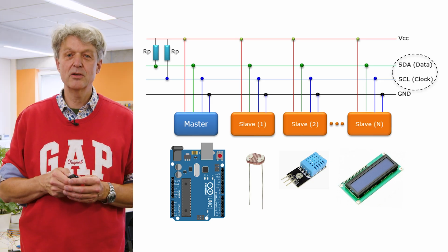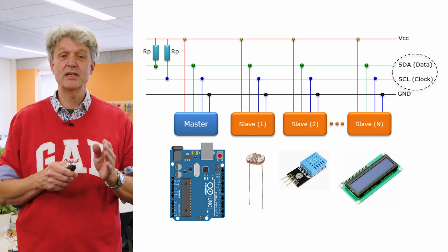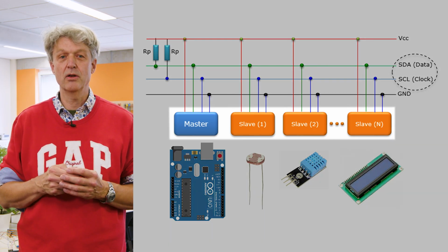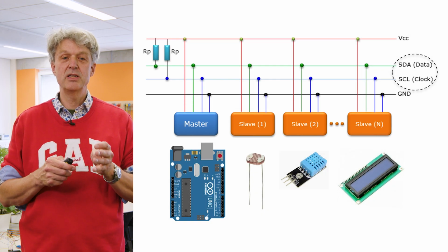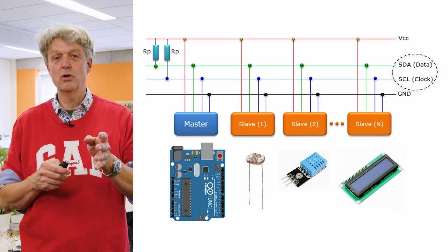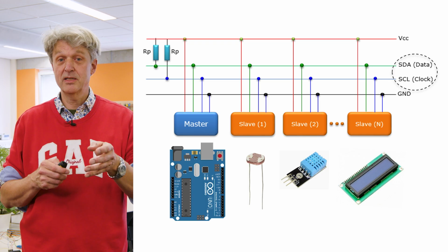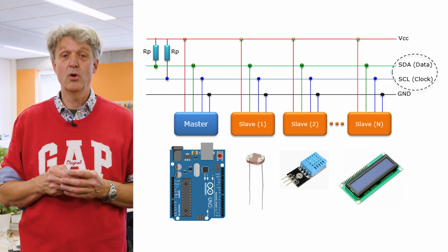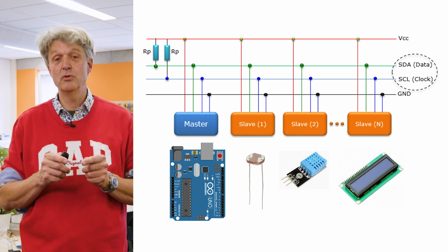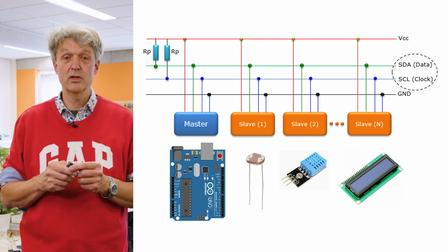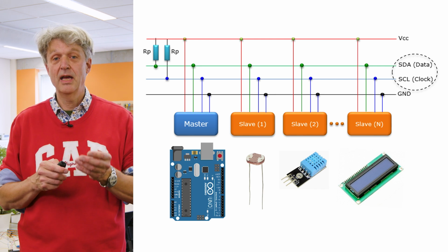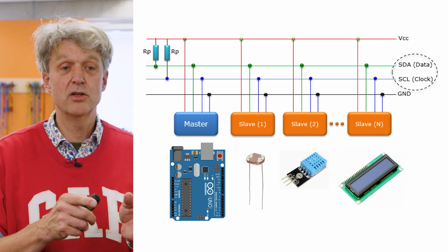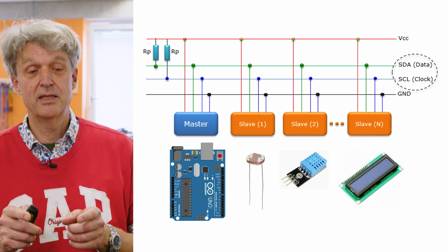And you can see that the data wire, but also the clock wire, is connected to all those boxes you can see over here: the blue one, and there's three orange ones. The blue one is basically the master controller of this so-called data bus, which is in this case again the computer, the Arduino we have been using. And the orange boxes are the sensors for light, for humidity, and even the display is connected. The controller can communicate to every single device using that data bus.